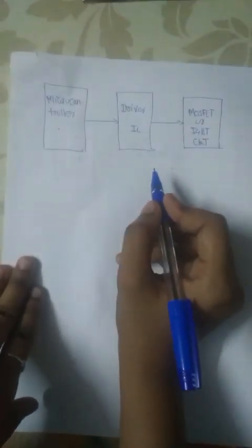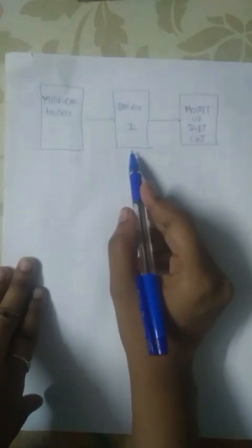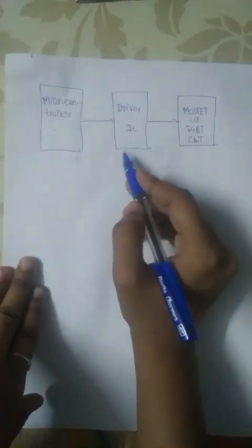If you have a huge power conversion circuit where the MOSFET drives a motor or something, then you have a power MOSFET. You definitely need to switch very fast. You need good driver current to the gate. So in this case, the driver IC, the gate driver, is the most important.